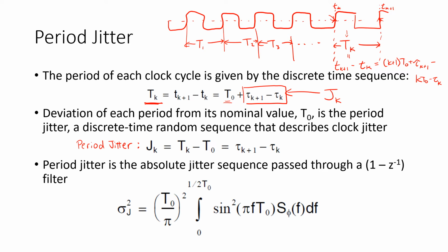You would see that most of the time, this subsequent second rising edge would be very close to t0 seconds after the trigger, but it wouldn't be perfect. It would vary somewhat, and we could measure that variation over many, many measurements with a high persistence on the oscilloscope and take its RMS value, and then that would give us a statistical measure of the period jitter, RMS.